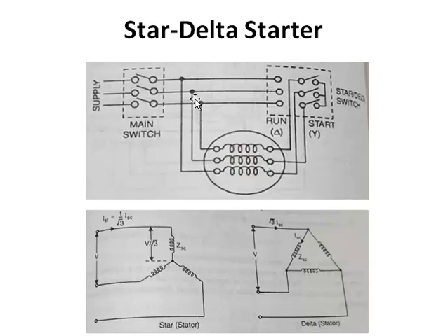You can see here 3 ends are connected to the supply, and when the other 3 ends make contact with this one, this point would be connected to this point, which would be connected to this terminal. If you see, all of them are short circuited. So one end of the windings is joined and the other 3 are open. So we know what connection that is. It is a star connection.